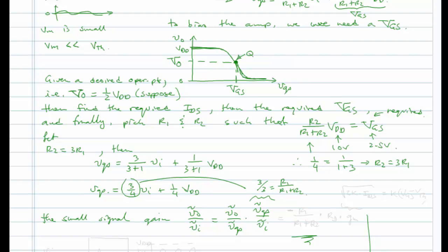So adding in this weighted voltage summer at the input has an impact on the overall voltage gain, and you need to include that. But the benefit is that you're able now to supply the bias voltage to the gate, capital VGS, from your battery or your power supply source, VDD, rather than requiring that it comes from your input signal, VI.